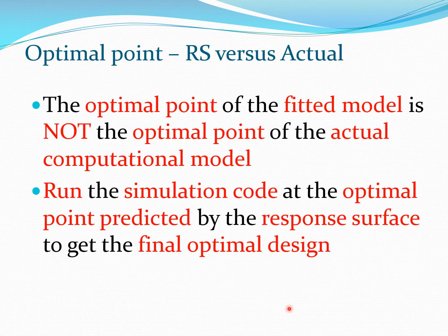Now one very important concept to remember, and this is where some neophyte researchers make mistakes, is that the optimal point of the fitted model is not the optimal point of the actual computational model. And whatever fitted model you have developed is just a guide for the actual function.